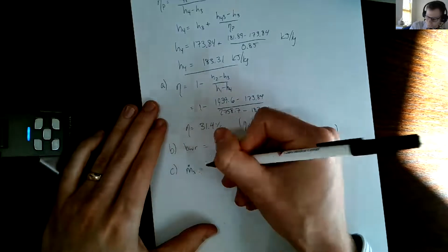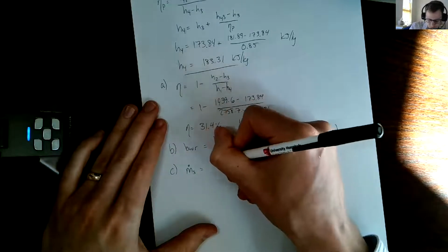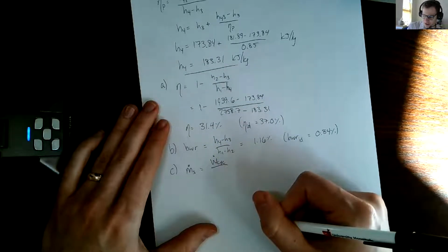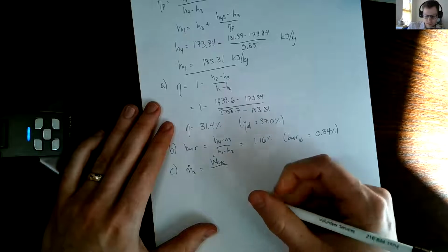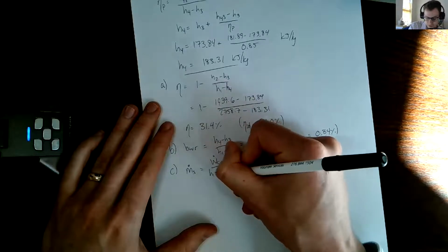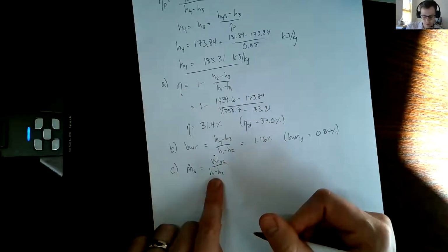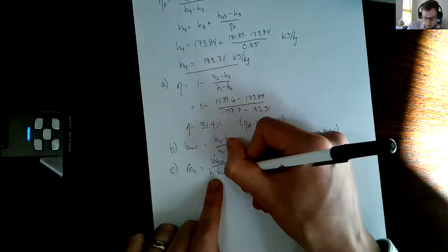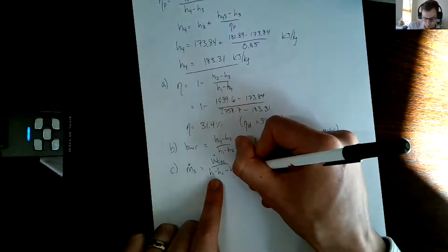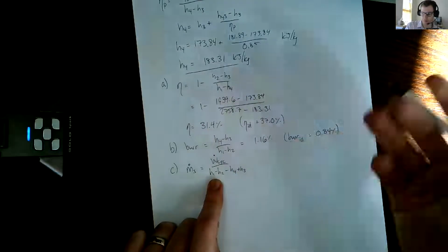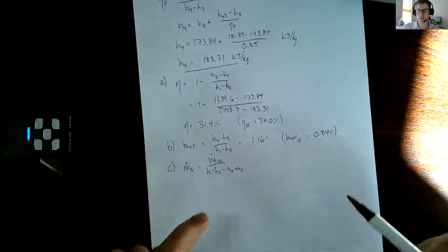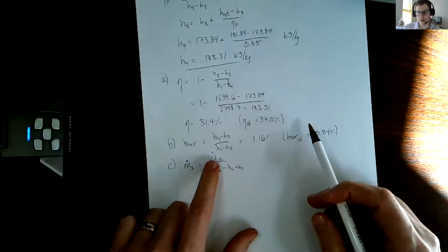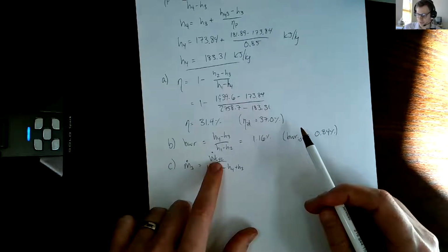Mass flow rate for the steam. Remember, we got this from before, from looking at the net power of the cycle divided by the enthalpy differences. So this is the power out from the turbine per unit mass, and then minus the power into the pump per unit mass. You can look at the example from last time to see how this is all spelled out. The net power for the cycle was again 100 megawatts.